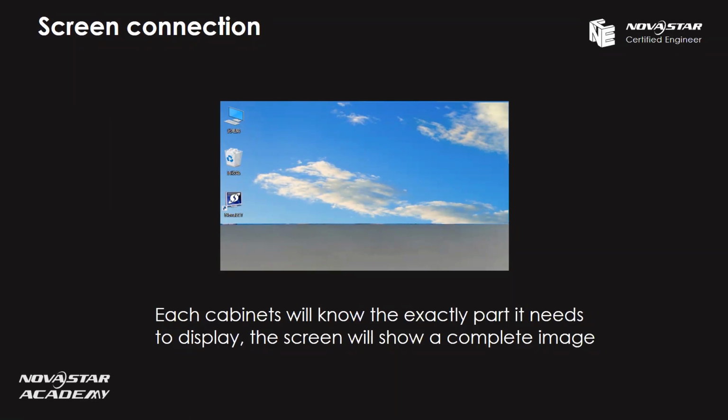They may want to display a video, or add different content on the screens. So basically, there are two ways. One way is to add a video processor. With a video processor, we can do the scaling function, and we can also open multiple windows or layers on the screen and just add content on the layers.